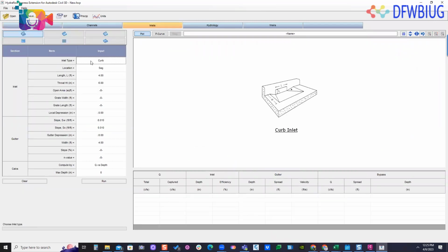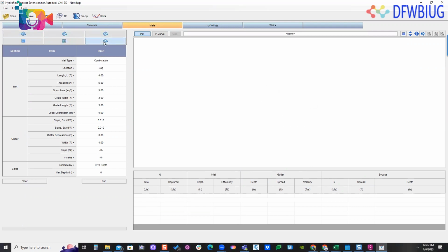If I'm doing inlets, you can do inlet in here. So you can size inlets. And you got different types of inlets in here. Notice that some of these have grates, slotted, drop inlets, right here, drop curb. So you do have those flexibilities. You're just plugging in information. The most important information is getting the slope right and what your Q is coming into it, and it'll tell you the information.